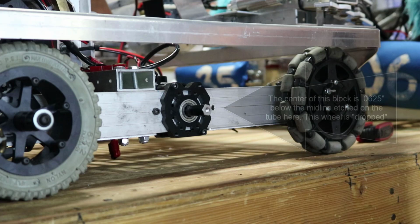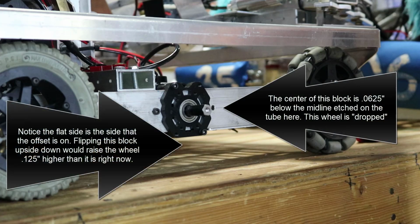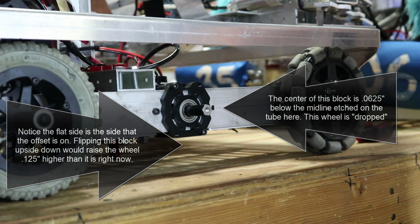The bearing blocks that you buy from Vex and West Coast Products have a 1/16 of an inch offset built in, where the center of the wheel sits that far away from the center. It is easy to flip these upside down by accident, but there is a correct and incorrect way to flip them based on your design. We want our outer wheels to come up 1/16 of an inch and our center wheels down 1/16 of an inch for a total drop of 1/8 of an inch.